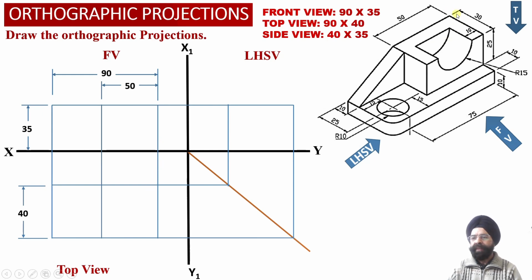So we can check this rectangular block is located towards the right hand side face of the solid over here. So from the right hand side face of the solid we have marked a distance corresponding to this rectangular block, and we have obtained a vertical projection into the front view projection, and this projector line has been extended into the top view projections as well.